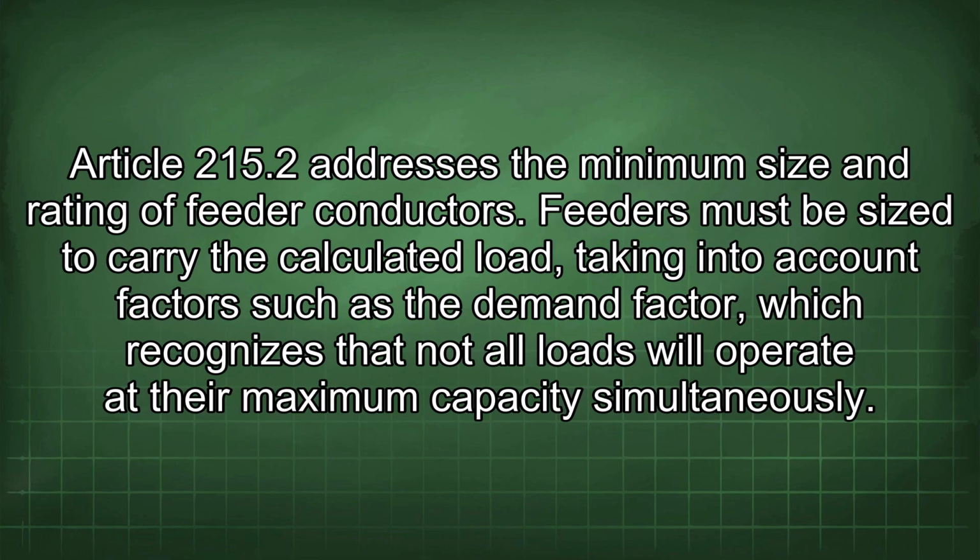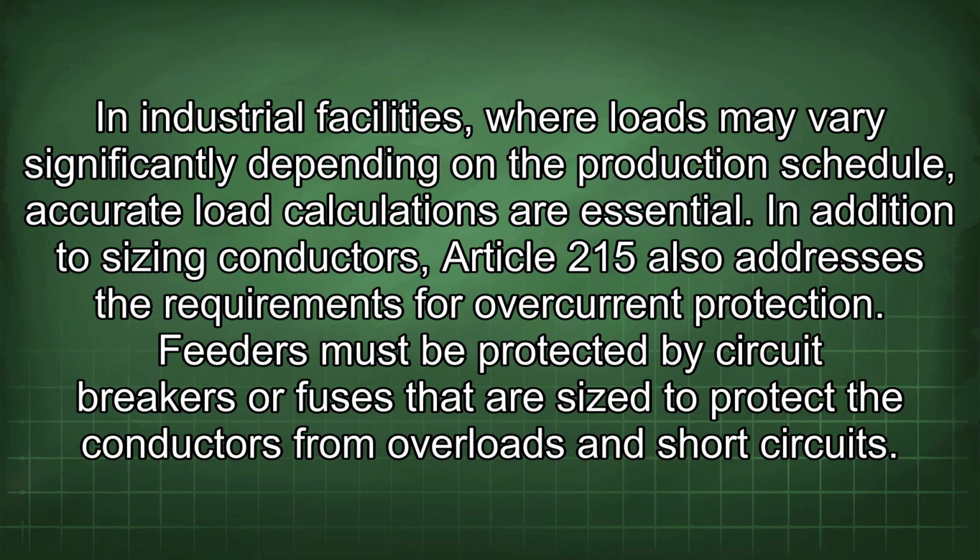Article 215.2 addresses the minimum size and rating of feeder conductors. Feeders must be sized to carry the calculated load, taking into account factors such as the demand factor, which recognizes that not all loads will operate at their maximum capacity simultaneously. In industrial facilities, where loads may vary significantly depending on the production schedule, accurate load calculations are essential.